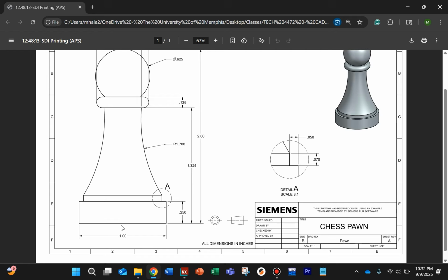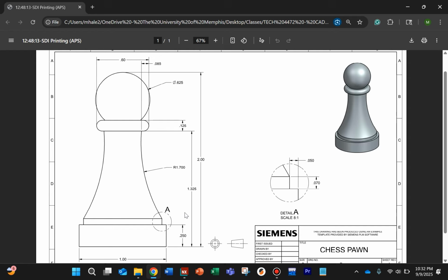So we don't want to put in just half an inch. We actually want to put in 1 divided by 2, since 1 inch is what we're told on the drawing. That's the final dimension that we're looking for, 1 inch. It's just that the sketch is dividing that by 2 because it'll double to create the final part.